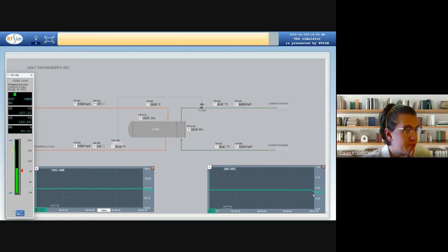Accordingly, there is even more liquid in the product outlet, but our goal is for the distillation fraction to be 0, so that pure liquid flows. To get closer to this value, I suggest completely opening the cooling agent flow. To do this, let's switch our temperature device from automatic mode to manual mode.